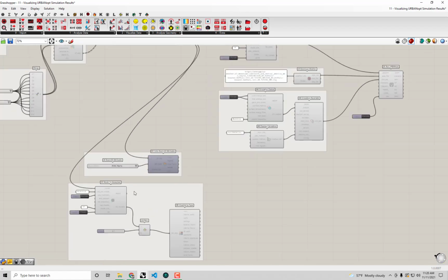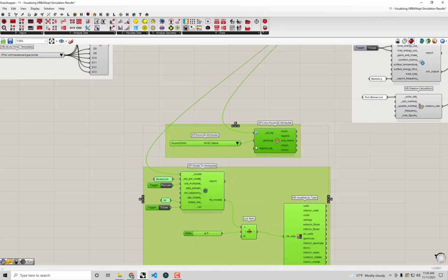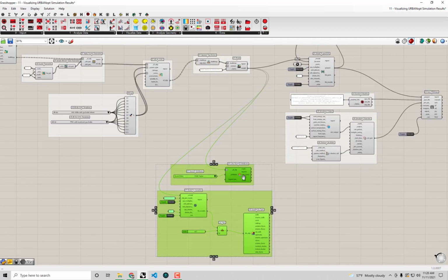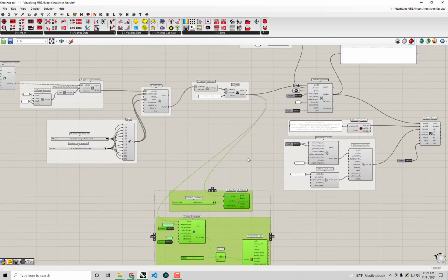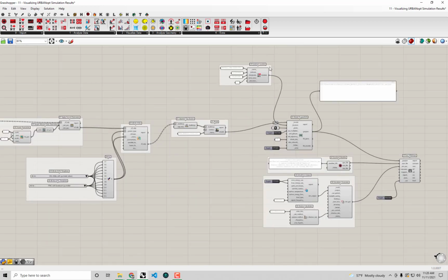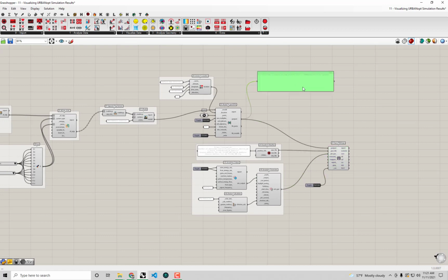And to be honest, I don't think I need all of these extra visualizations that I'm doing down here of converting over to Honeybee. We've already understood how to set up our model this way. So we're left with just the definition for creating our Dragonfly model, exporting that to GeoJSON, and simulating that within URBANopt.